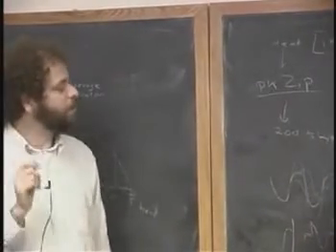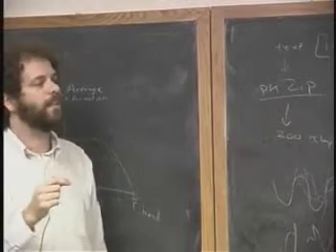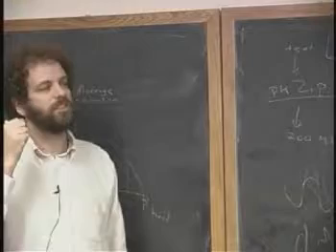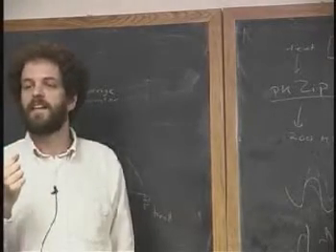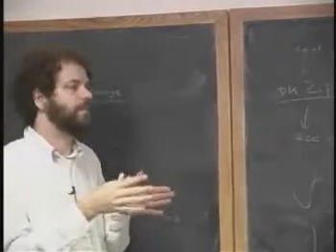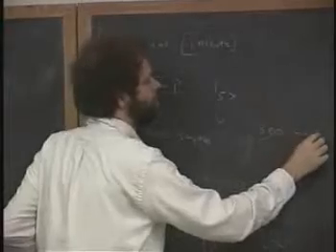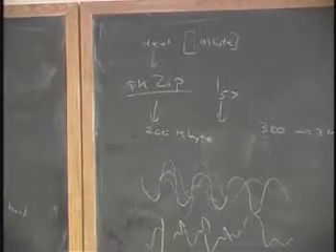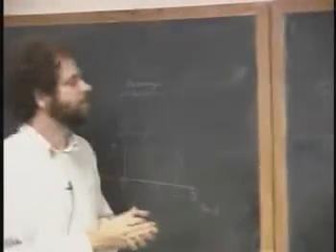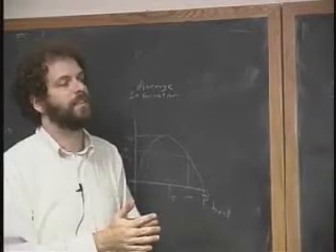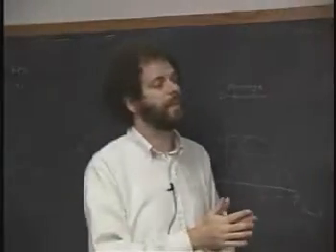How many of the rest of you have ever listened when a 56K modem is on the line and you pick up the line by accident? What's that sound like? Sounds like static. And that's why. Because the 56K modem is packing into the spectrum of the phone line, which is roughly from 300 hertz to 3 kilohertz, which is a very small spectrum to deal with. It's trying to pack in as many bits as it can. And as many as you can actually do is 56K. And as a result, what you hear sounds just like noise. And you can't tell the difference.